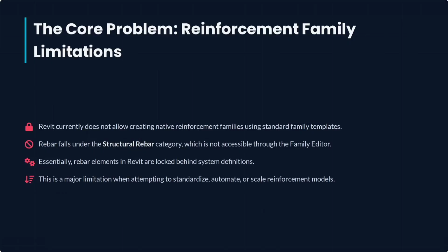Let's start with a simple but well-known problem. Revit currently does not allow creating native reinforcement families using standard family templates. Rebar falls under the structural rebar category, which is not accessible through the family editor. This is a major limitation.